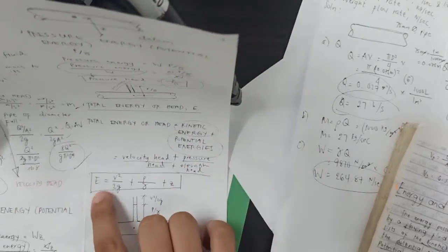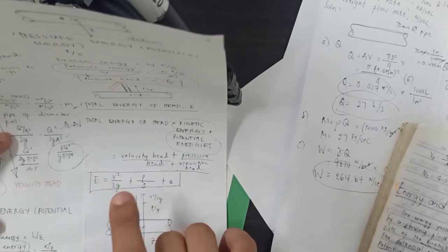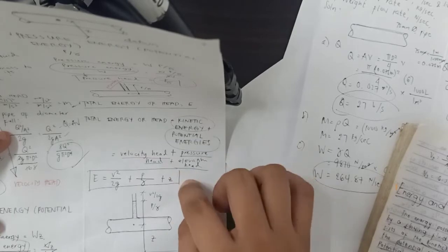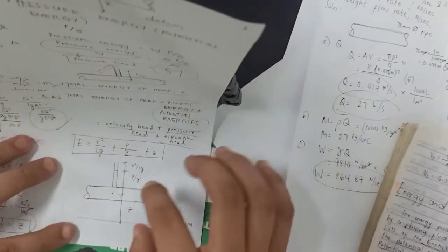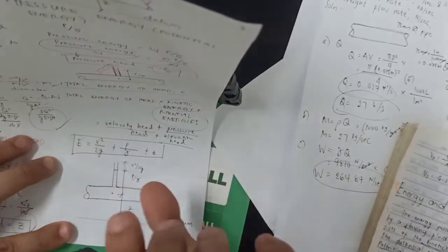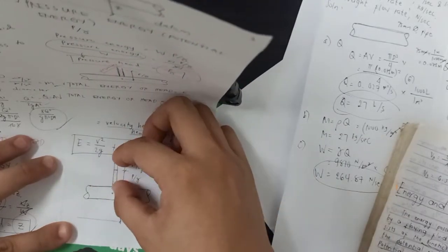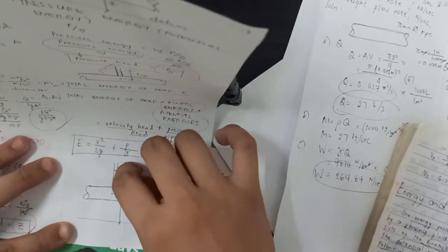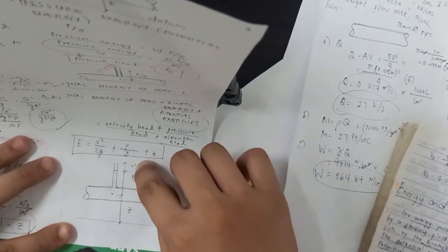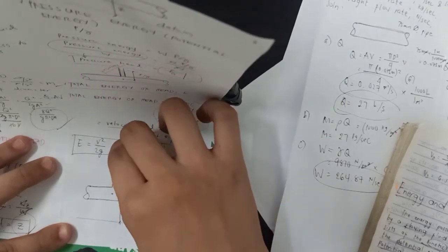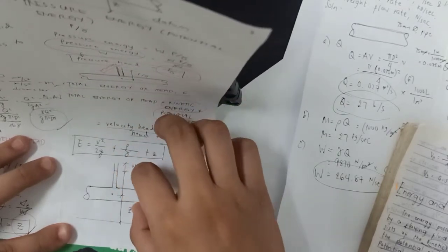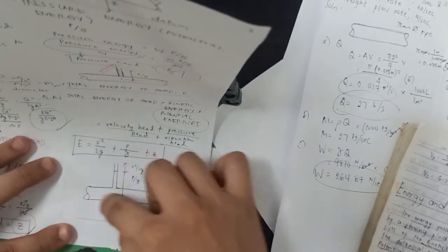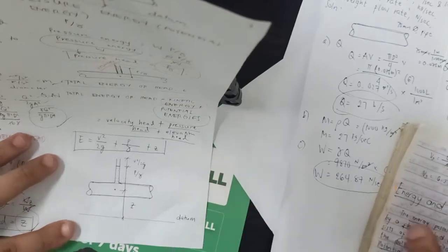So, therefore, our E or total head equals V squared over 2G plus pressure over unit weight plus Z, or elevation head. The illustration shows a datum and an elevated vessel with a piezometer, imaginary or actual. So we can have the measurement V squared over 2G at the upper part, and the fluid pressure over unit weight, and the center of the pipe section is Z from the datum.